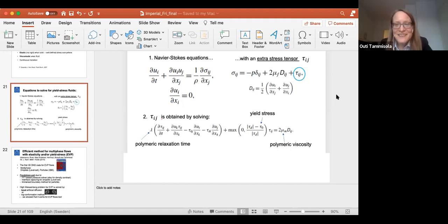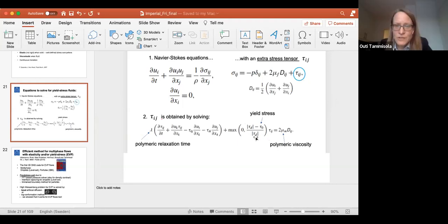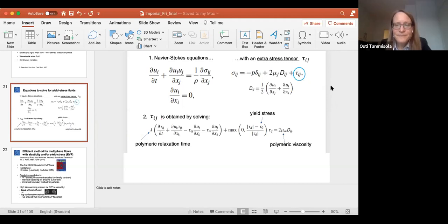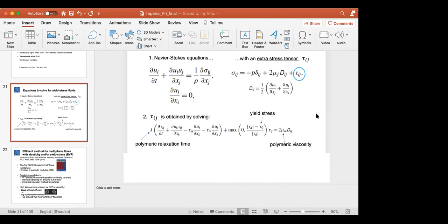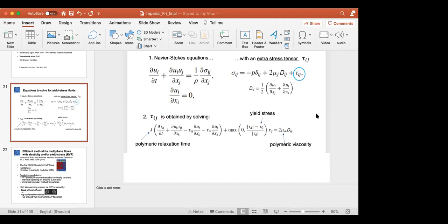Yeah. So it is a physically motivated equation. Physically correct. But maybe your question was about this norm. So this is actually the von Mises criterion. It's a two-norm of the deviatoric part of the extra stress tensor that we have here. I should have probably written it out. So this is how it generalizes also to 3D. I see the idea, the motivation for doing this. Just what kind of principle we need to stick with in doing so.